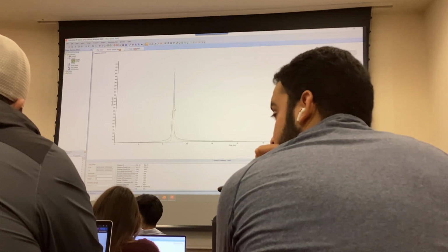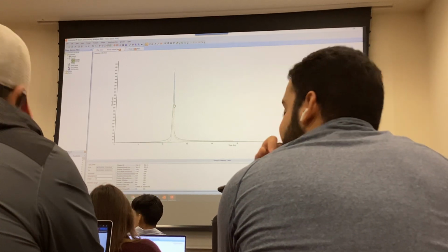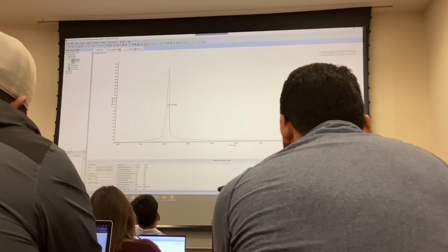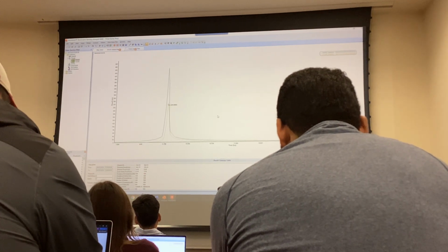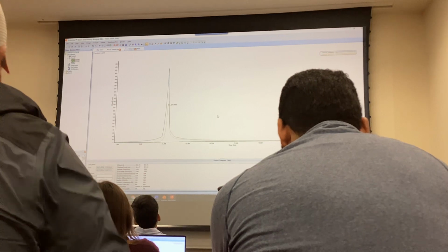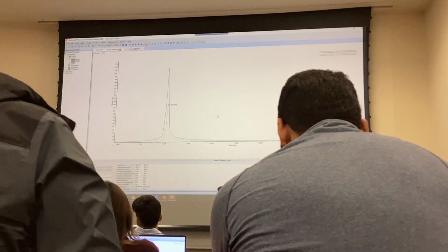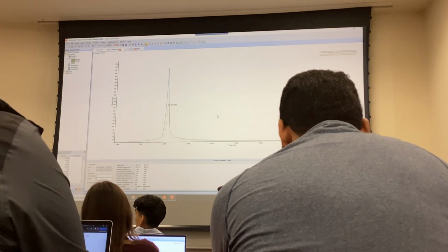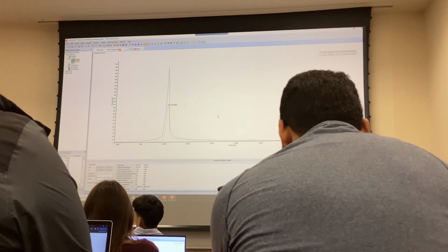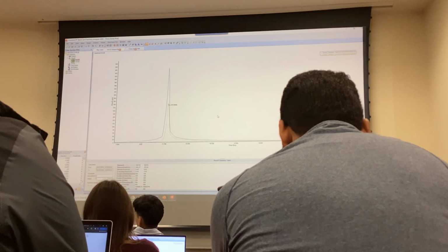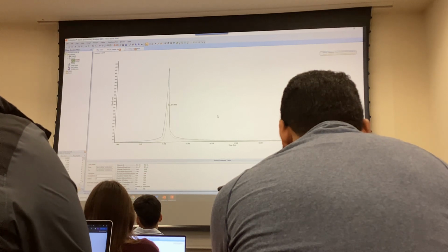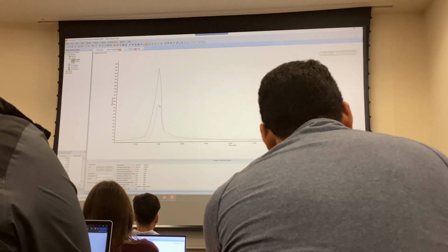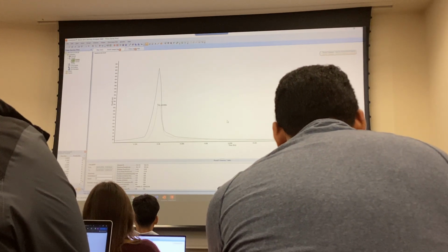Okay. So let's say this is my pre-development peak. You click on the pre-development peak. You're going to come here and click on that pre-development peak. It's going to give you a coordinate. And what does that coordinate tell you? The coordinate of the peak, right? So the coordinate of the peak has two things. One is the time. The other one is the flow. That's right. So what you want to do is come take a look at the QP, right?